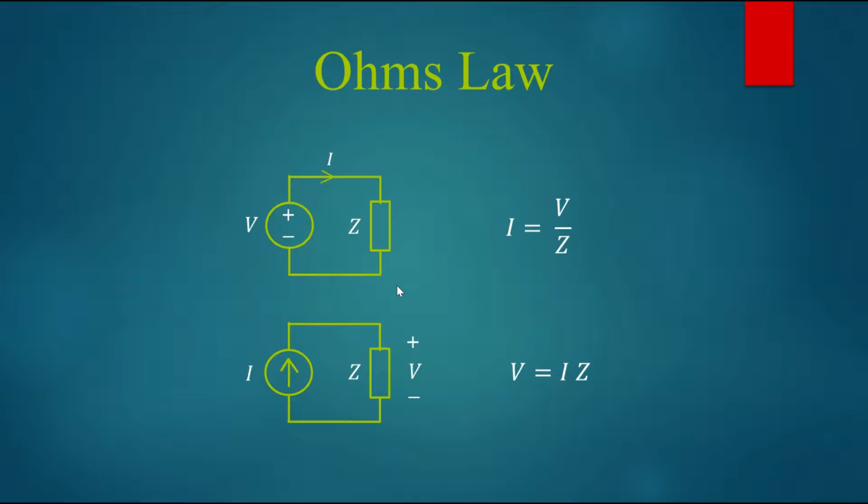All right, so Ohm's law, very quickly. You put voltage across some impedance. Now, a specific case, this could be a resistor, but in general, it could be a resistor, a capacitor, an inductor, or something else. You put voltage across it, and some current flows according to Ohm's law, which is shown by this equation here. The current, I, is equal to the voltage divided by the impedance. So the higher the impedance, the bigger the denominator, and therefore the smaller this number, and the current is lower. So more impedance means more impedance to the flow of current, less current.